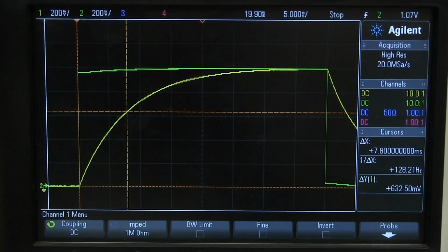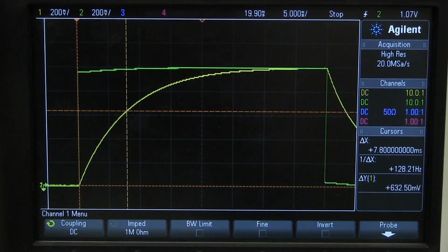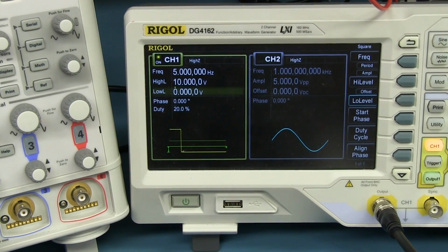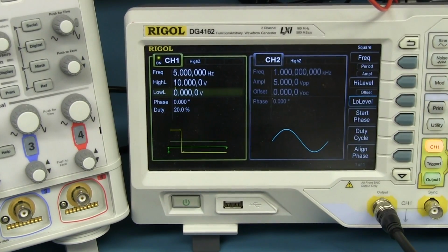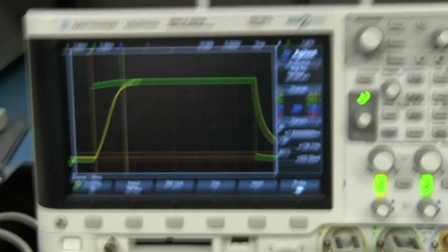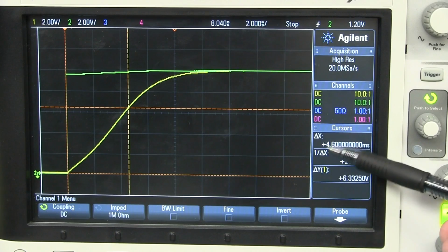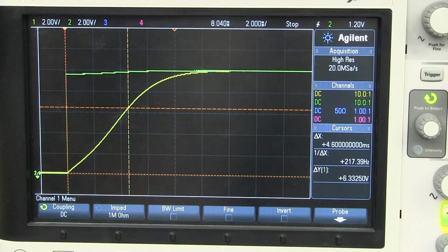And, well, that's not a mistake. As we've seen, capacitors can vary with bias voltage and also other things like just the basic applied voltage. Now let's check this same Y5V capacitor from 0 to 10 volts instead of 0 to 1 volt. Once again, there's no DC bias here at all. What do we get? Wow, look at it. It looks substantially different. And there we go. Look at that, 4.6 milliseconds. Goodness, our capacitance once again has like halved.